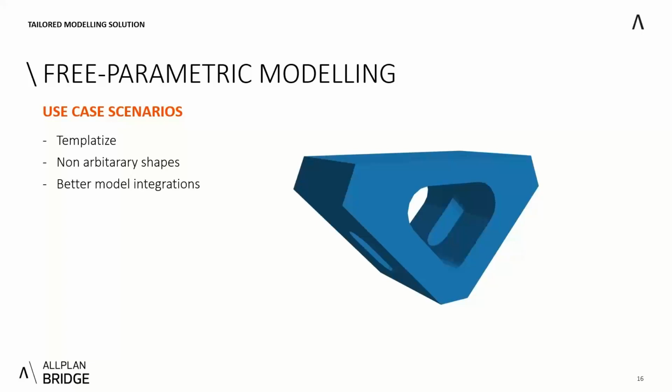By using different approaches such as partial import and export, you can reuse an element like this one multiple times. This was created using free parametric modeling, so we can create it once and save it as a partial TCL and use it in different projects. Basically we are templatizing a lot of operations done here, such as the Boolean operations and the variations in height and so on. All that is abstracted into one object, and this object could be used as a partial TCL in different projects.